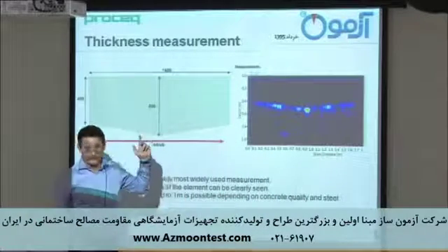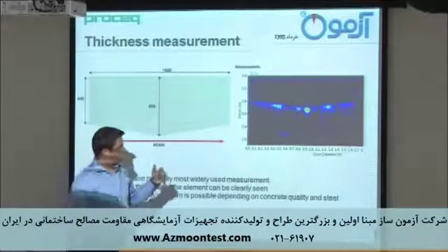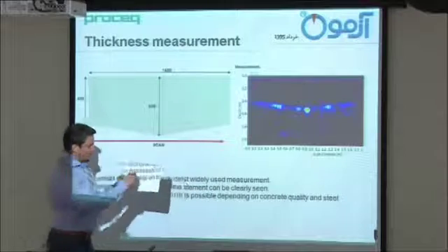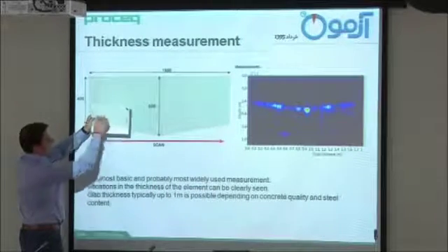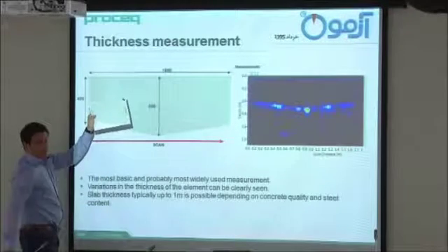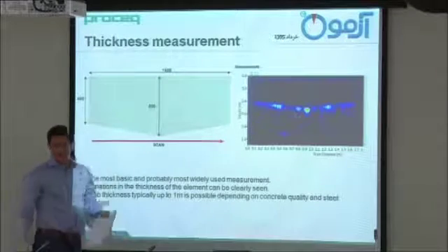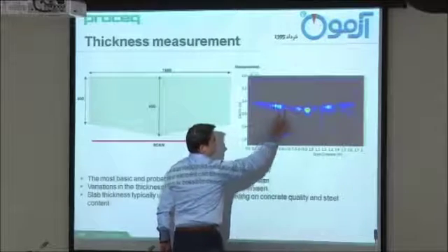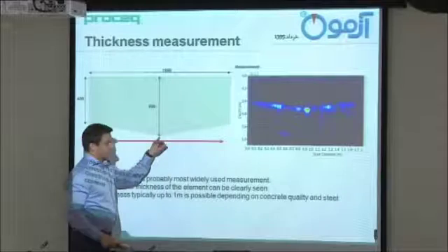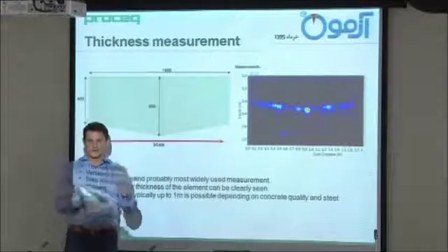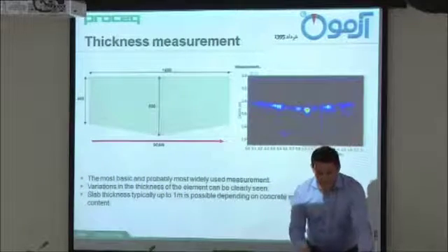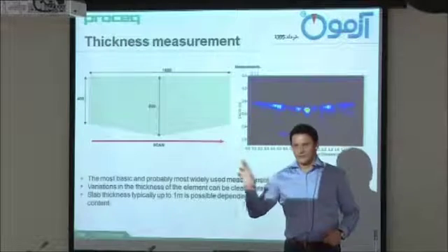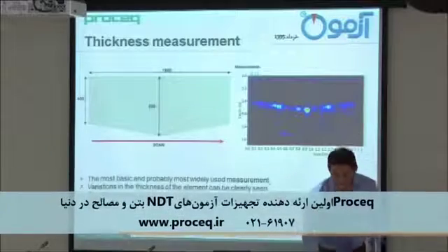And now you can see something very special here, which is very informative for the future when you do tests. If it is flat, we don't talk about angles, it will bounce back like this, the ping pong. The moment it is like this, it will bounce back in a different angle. So here you can see from bouncing back the waves are coming together, so you will have an echo here, and the biggest echo you will have here, because here is the corner, because it's not rectangle. You will see this quite often if you do tests, so first check how the angles are, and then you will also recognize, okay, this echo is correct, this echo doesn't make sense, it's just because of delamination and something is going through.